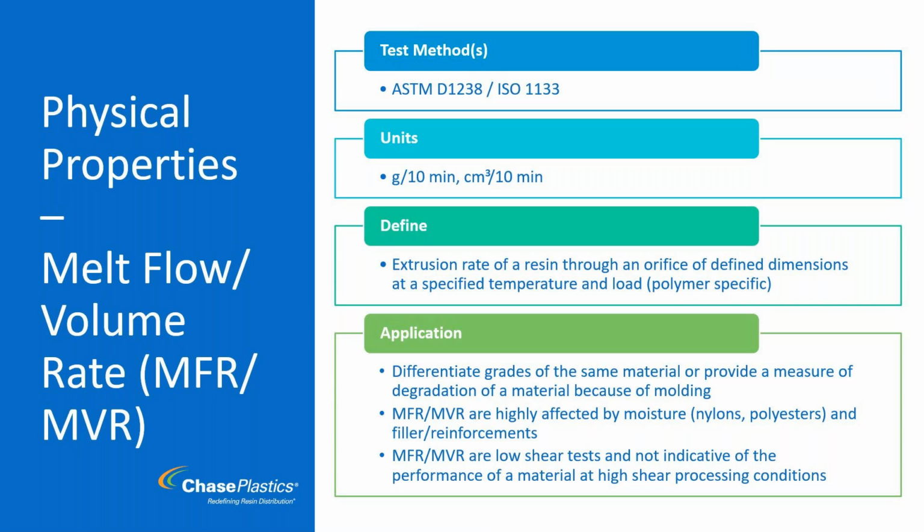I think we can also infer some performance properties on a material based on flow rate, and this isn't equal across all polymer types, but say we're trying to fill a cavity with an 8 melt polycarbonate and it's not quite full, so we move to an 18 melt or 19 melt, which is standard injection molding grade melt flow rate for polycarbonate, and we get almost full by switching to that, but we're not quite there, so we switch all the way up to a 40 melt, or the really high end, like a 65 melt, right?